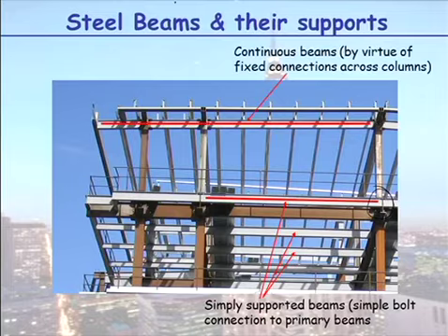Then up on this top one, I don't know if you can see there's a thickening to the flange, top and bottom. So that would be where the actual beam itself is either bolted at the flange, as well as being bolted along the web, or fully welded. I'm not sure if that's fully welded up there. So this member now, because it is rigidly joined, is effectively a continuous member through here.